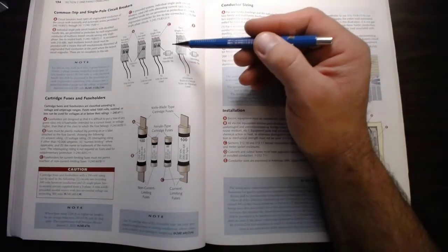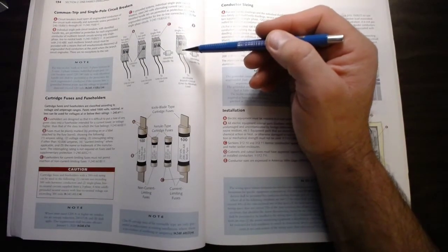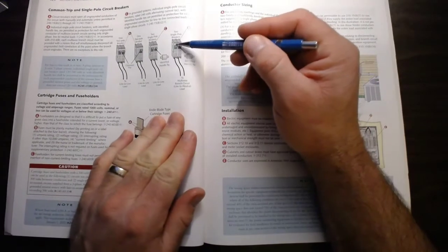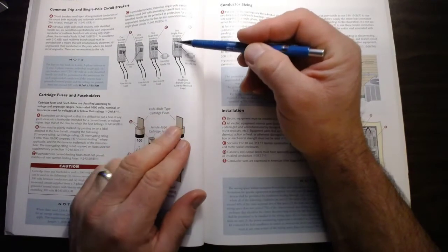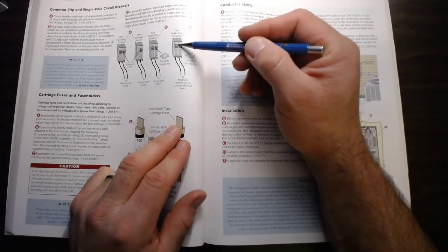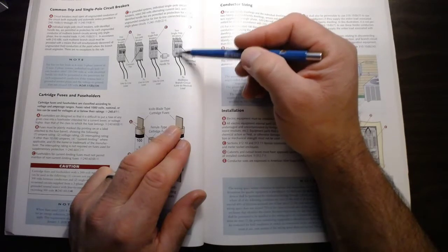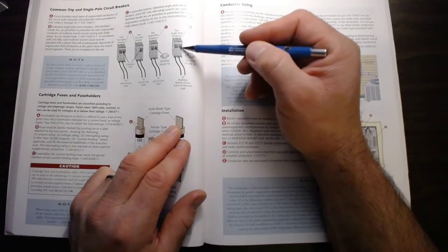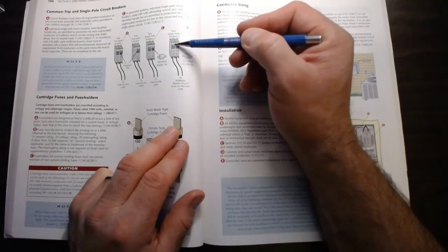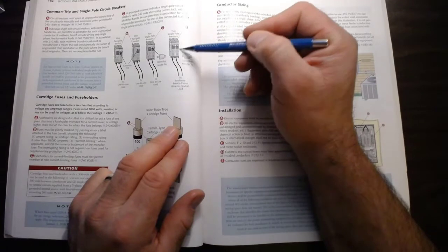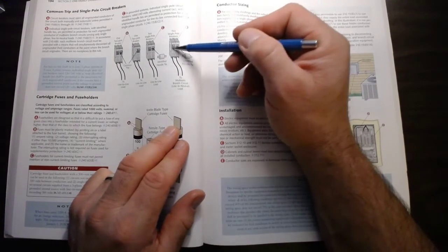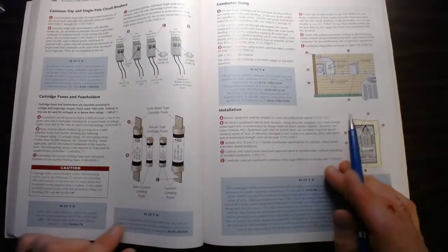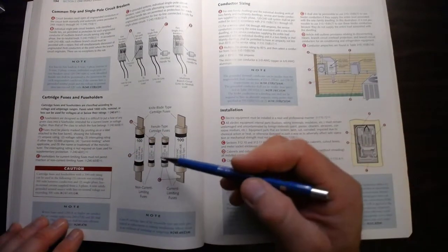There is a circuit breaker in some of the residential panels that has 4 circuit breakers together, and it's a 200 amp service main breaker. So it's got 2 100 amp breakers put together, but they're installed in such a way that it provides a 200 amp. But it looks like 4 breakers installed under one common throw, but it's a 200 amp breaker in order to give it its 200 amp rating. That's just the way one manufacturer does it.